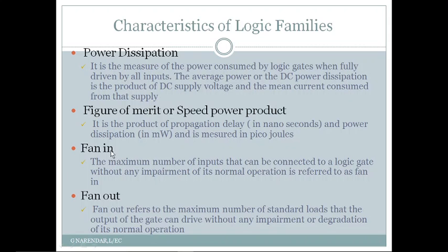So next we have one more characteristic, that is fan-in. Fan-in tells us the maximum number of inputs that can be connected to a logic gate without impairing its normal operation.